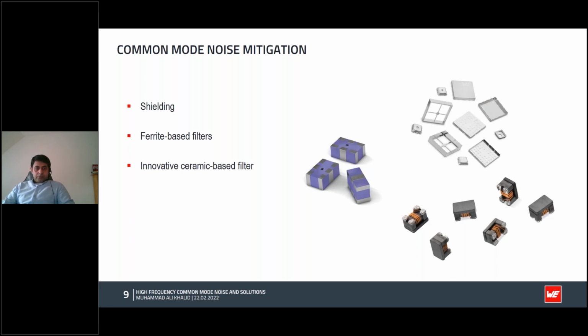Shielding, the first one, is perhaps the most commonly known solution against radiated noise. For lower frequencies it works quite well, but at millimeter wave frequencies, the openings in the shielding can be a potential source of RF interference themselves. Filters and chokes are very effective means of protecting the data lines. They can substantially enhance the characteristic symmetry of the transmission line and thus contribute to increased interference immunity while at the same time reducing the emitted interference.